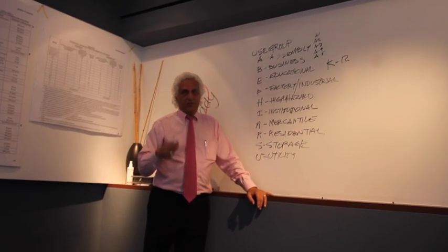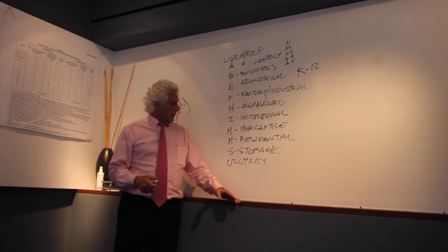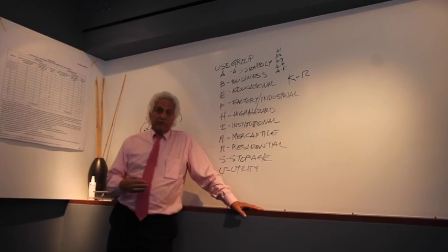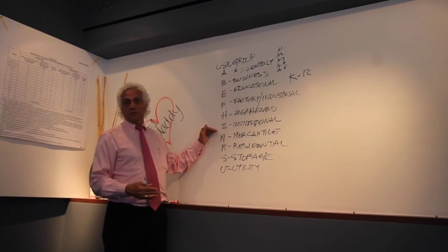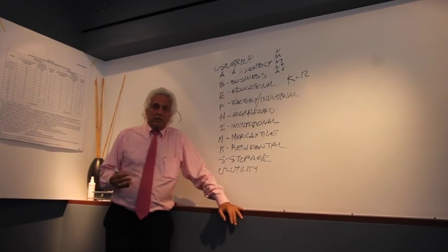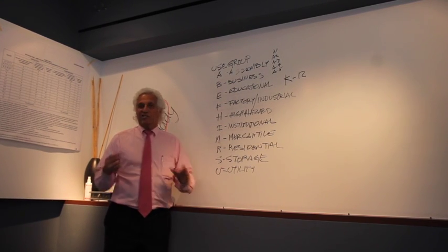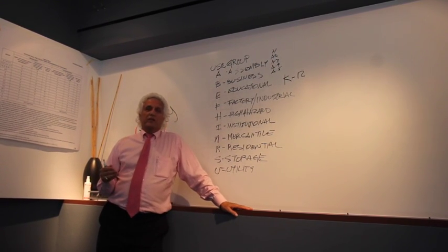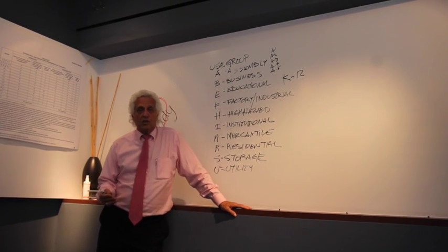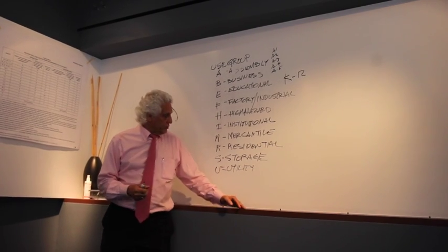As well as high hazard has an H1, H2, H3, and H4. Storage are, like the name implies, storage of materials that aren't high hazard. This is simple storage, warehousing, and so forth. Utilities is kind of a catch-all. They'll take things like water towers and things of that nature, substations for phone companies, for utility companies. Those are under the utilities.